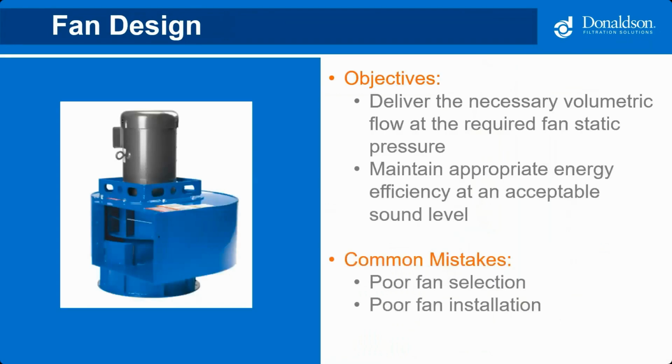It has two responsibilities. First, it's got to deliver the necessary airflow at the required static pressure to drive the operation of the system over a range of static pressures. Secondly, the fan should be able to deliver the desired static and airflow with an appropriate energy efficiency at a sound level that's acceptable. Fan challenges generally fall into two categories: poor fan selection and poor installation.